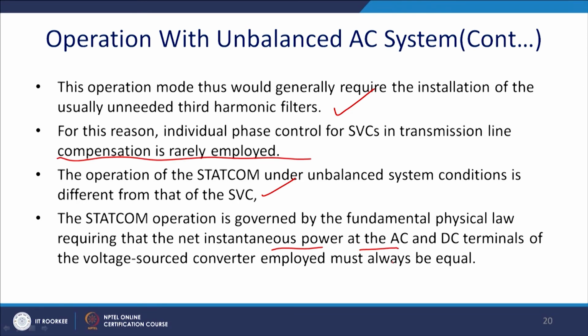Please note that point. The operation of the STATCOM under unbalanced conditions is different from the SVC. The STATCOM operation is governed by the fundamental physical law requiring that the net instantaneous power at the AC and the DC terminal of the voltage source converter it employs must always be equal. Thus, you can have unbalanced power or balanced power, it does not matter. So, it can better handle the unbalance.